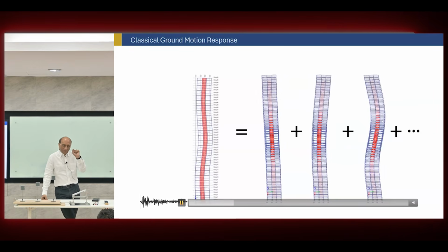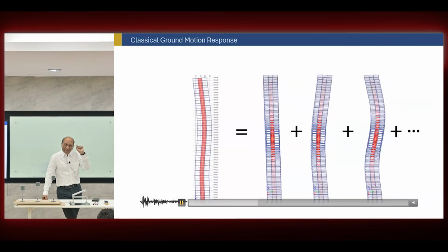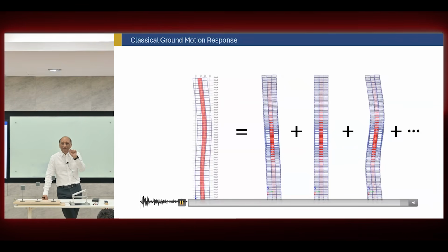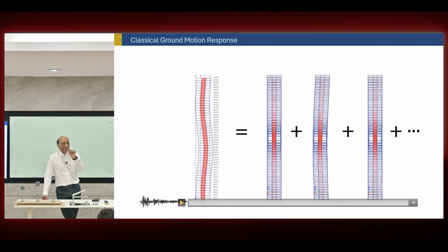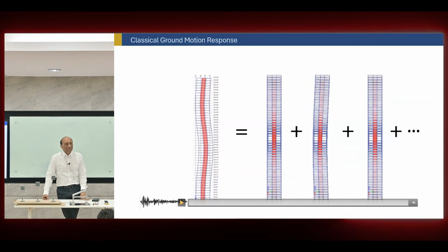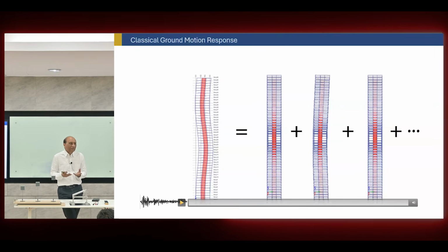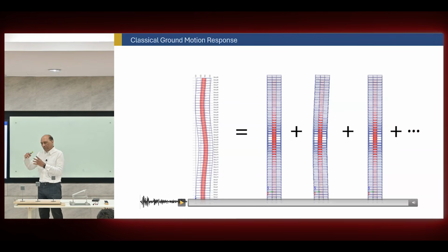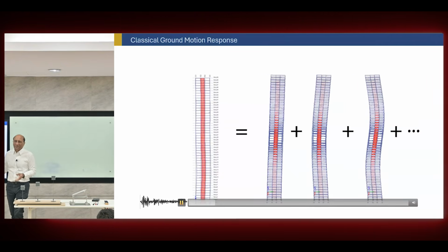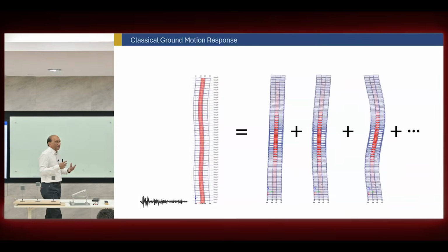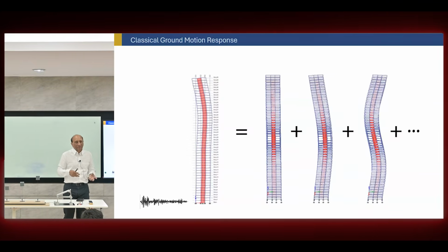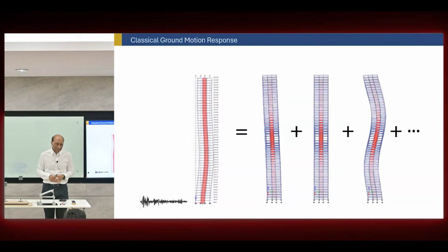So which means now we understand some important thing, that the natural modes will be very important when responding to external forces, like you see here, or external displacements. And those natural modes will combine together when they can. So we have to understand individual modes. We also have to understand their combination, and we have to understand which one will be activated, which one will be suppressed.